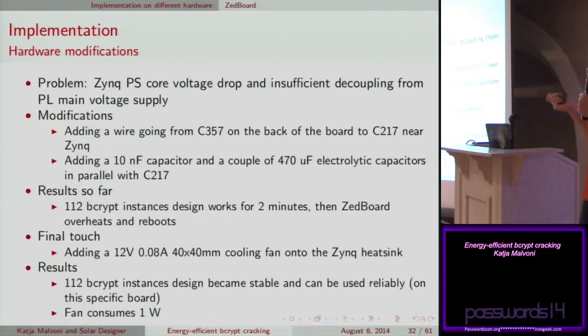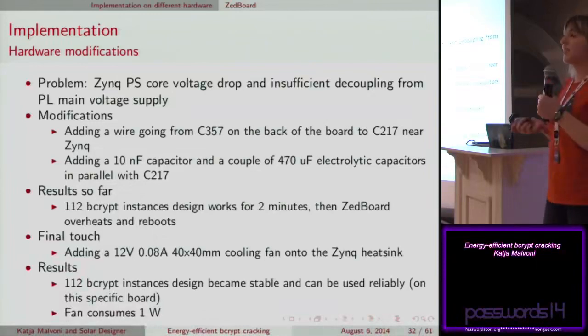So to solve this, we added a wire, which brings more current, so the voltage drop goes down, and we added capacitors, so that the decoupling is improved. And nicely, 112 instances do work. However, Z-board reboots because of overheating. So we added a fan, and at the end, the design works. It's stable and reliable.